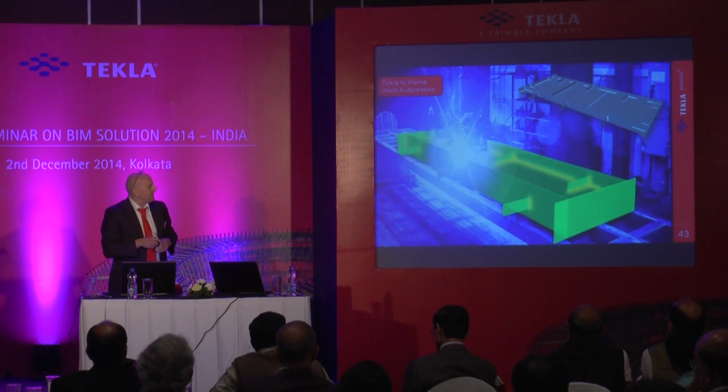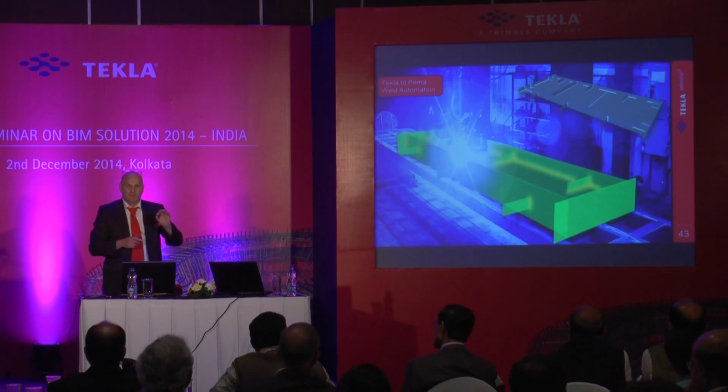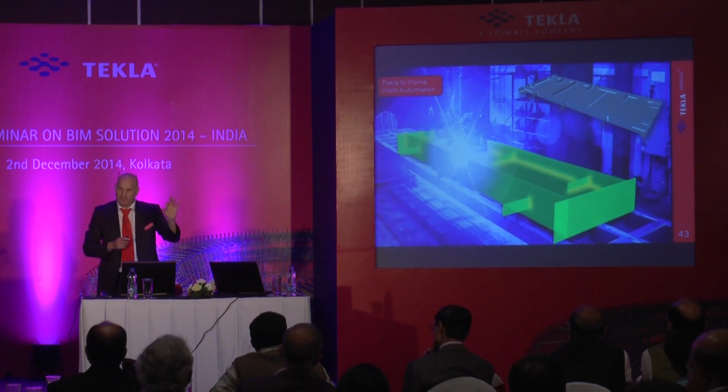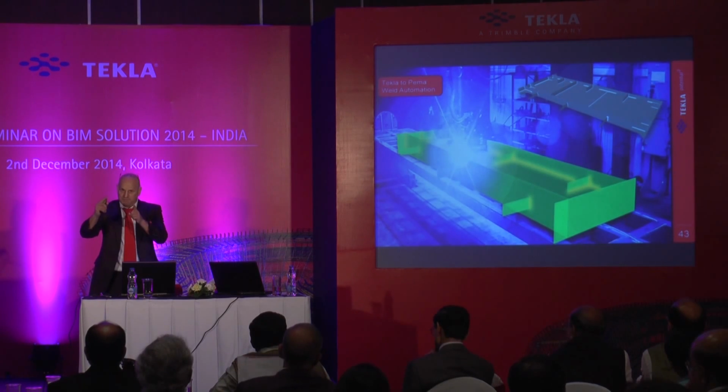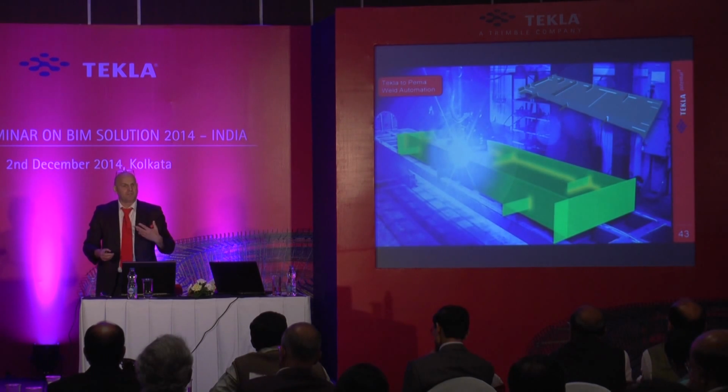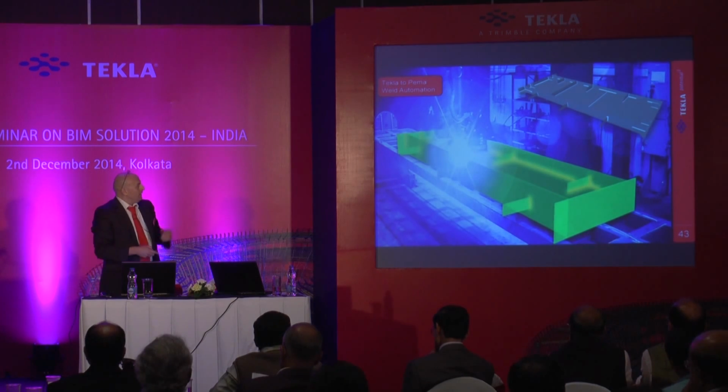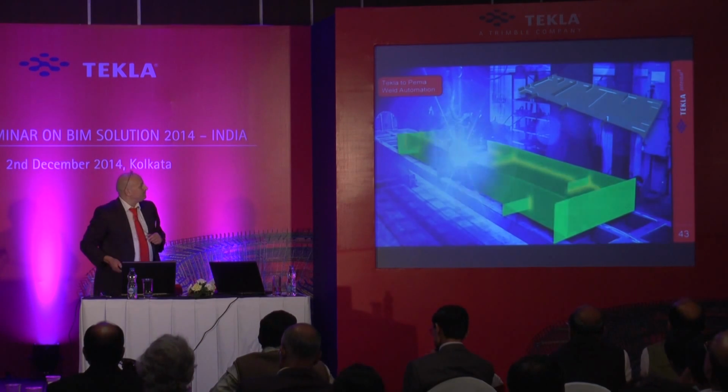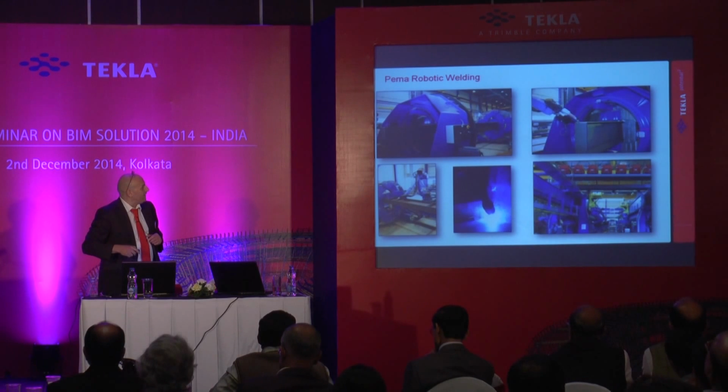What we're doing in Tekla is we're not just modeling plates and cuts and bolts, we're also modeling the welds themselves. So if it's a 6mm fillet weld, it puts it in there, and it's 100mm long, it puts it in. And then we can ask for a material list for that, what's the volume of welds required, and then we can link it down to the machine. The machines look like this, sort of automated centers.